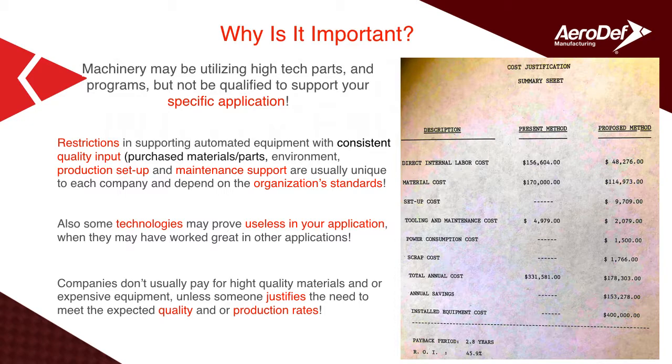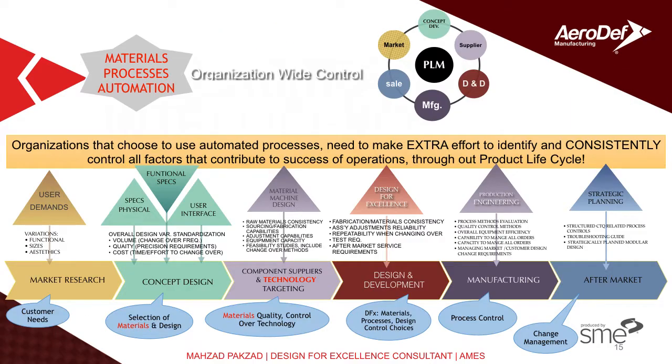And then we can do the cost evaluation. Usually you need to do the materials cost evaluation, tooling, maintenance cost, and estimated scrap cost, for finding out what is the final cost for your production.